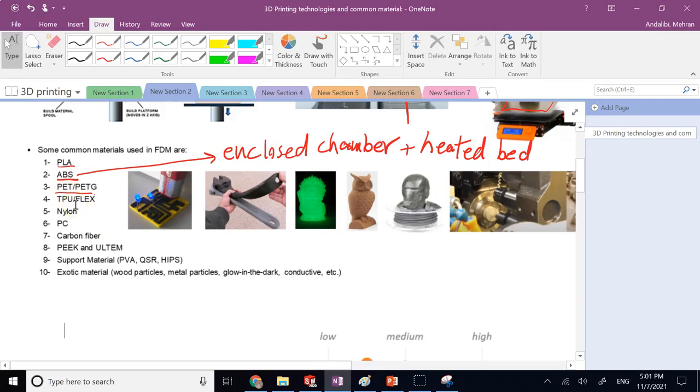The flow of it is not nice. The temperature for printing it is quite higher than ABS, PLA, and so on, so it is printed at a higher temperature. If you want to print smaller details, that's where TPU is not going to be the best. So don't count on printing small details with TPU, because the flow of it is not nice. It's not the easiest plastic to print, but it has really nice mechanical properties, very flexible.